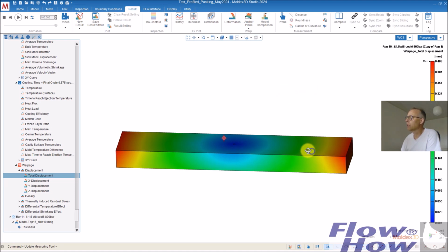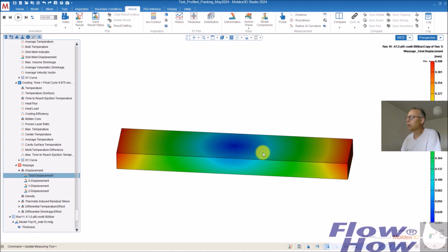It's getting the correct linear shrinkage, and linear shrinkage for this ABS is around 0.45, 0.5 to 0.65, or in that area, 0.7 maybe. And the linear shrinkage is not uniform. The linear shrinkage is just a measurement between 2 points.